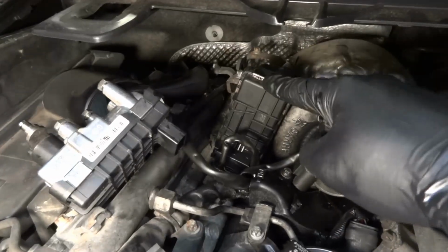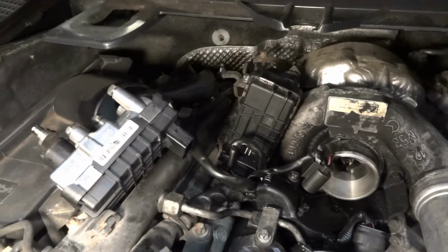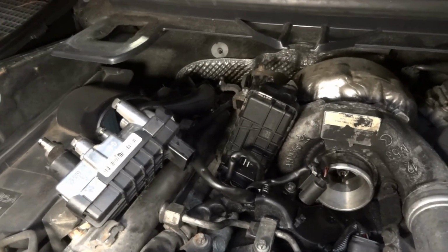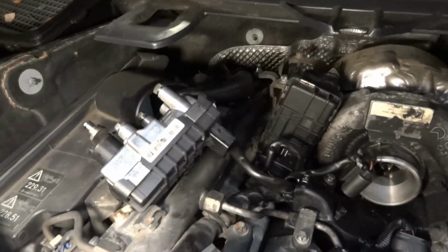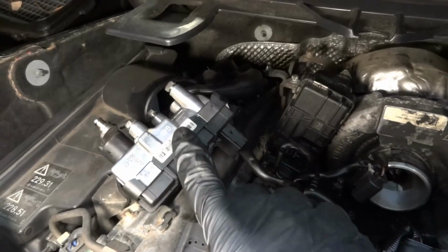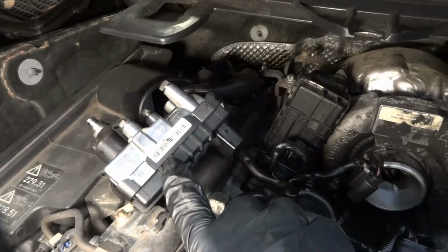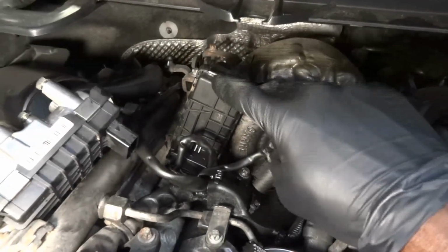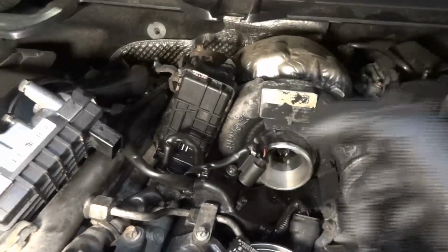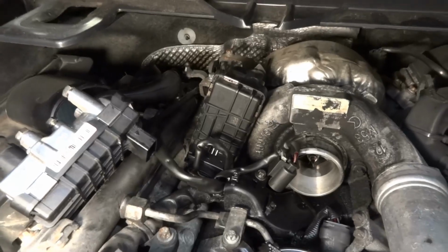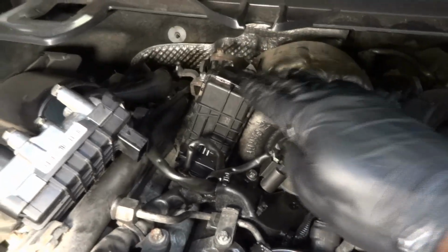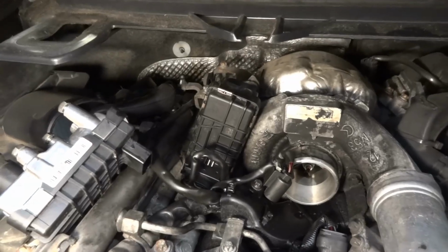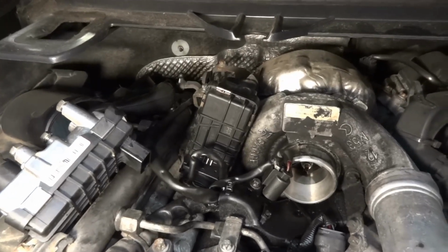So this actuator over here is defective. It's making a clicking sound when we press the F3 button on the scan tool. But when we connect this actuator and we press the F3 button on the scan tool, this one is not making noise. So the gears in this actuator over here are most likely binding. So now I'm gonna get this actuator removed. We're gonna get a new actuator. Hopefully we can find a new one. If we cannot find a new one, we're gonna have to get a used one.